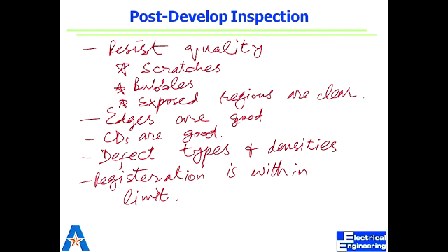And that would mean that there can be places where photoresist fails, and failing can be due to many different types of reasons. Some of the common defects are scratches on substrate, which would cause less adhesion of resist at that place. There can be physical bubbles left in the resist itself. It can be dirt or any contamination that might have been left on the substrate before we spin the resist. And so there is a whole long list of reasons why a resist or a pattern might fail, or what we call a lithography run might fail.